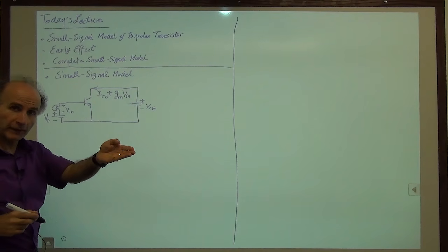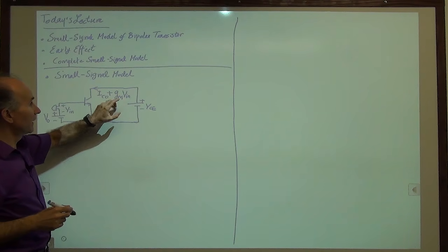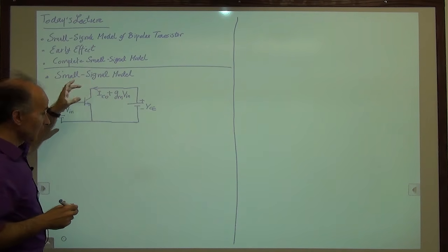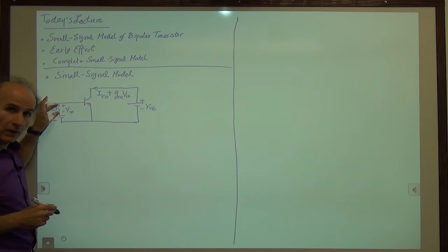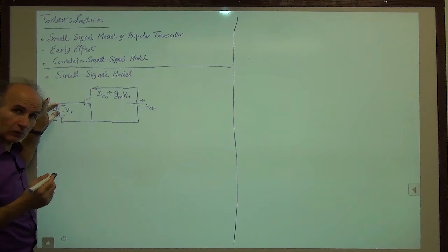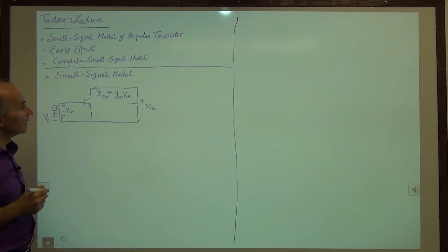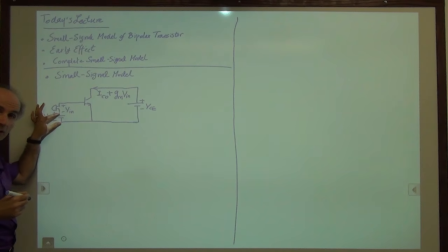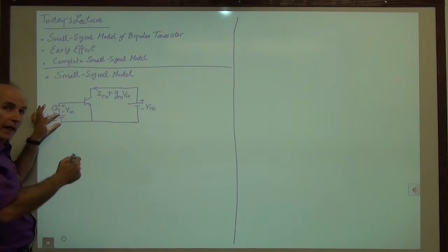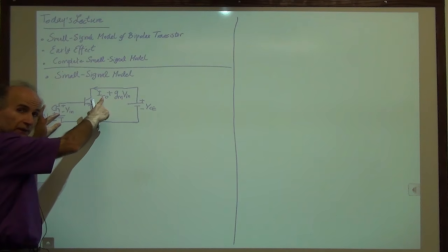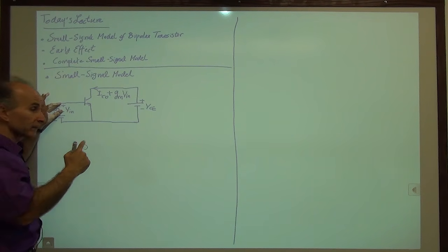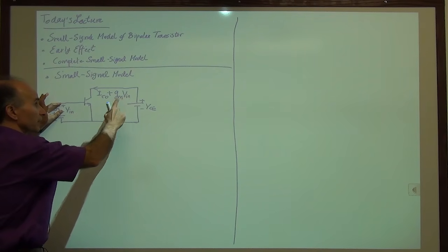What I just showed you a moment ago had Gm Vm sine of omega t, because Vm sine of omega t was the voltage of the microphone, which we now, for simplicity, call Vin. All right. So this is what we have. We have a bias voltage for the base emitter, and in response, we have a bias current in the collector. On top of that, we have a signal voltage, Vin, and in response to that, we have a signal current, GmVin.